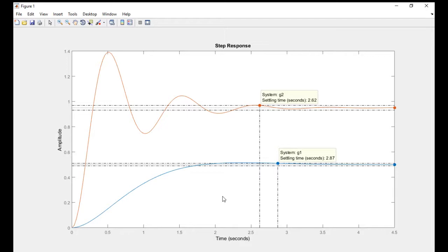And we're seeing beyond the overshoot. What else are you seeing? Sir, the peak amplitude and time. You have less time to reach the peak amplitude. If you compare, the other one doesn't have a peak amplitude. There's a slight overshoot. All right, so you're saying that there's a shorter time for the peak overshoot. All right, let's note that as well. So that is noted.